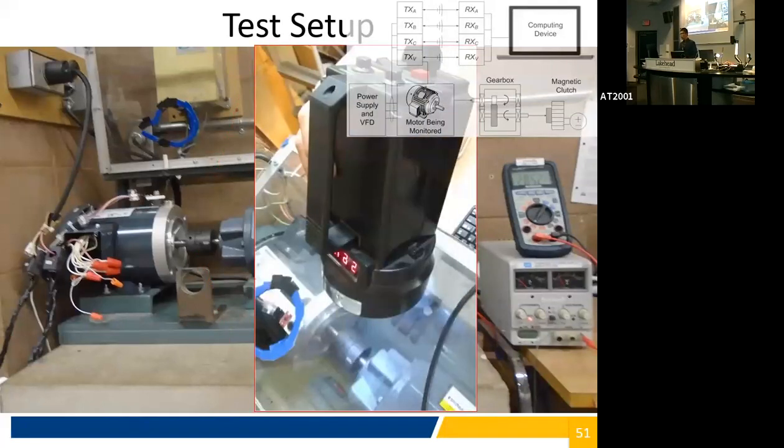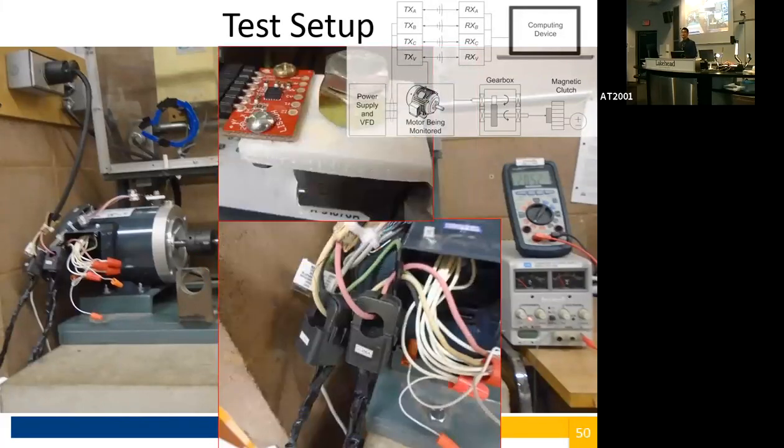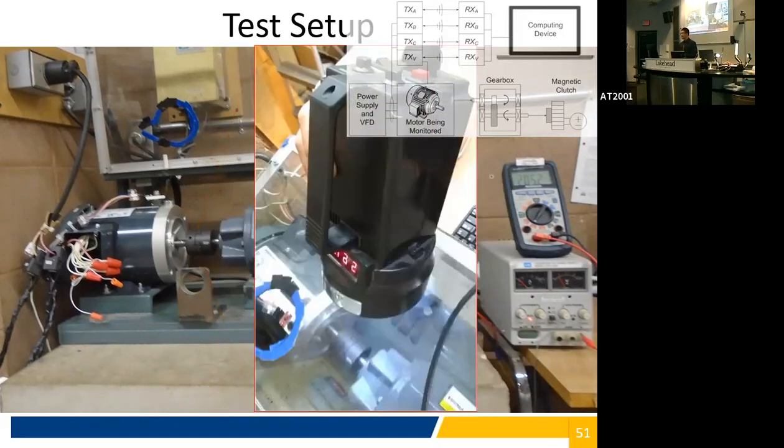And also, since the vibration was used to determine the speed, we did extra steps to confirm the vibration really corresponded to speed with a strobe sensor. So this is not part of the smart sensor system, but it was used as an additional verification where we shine a strobe light of a known frequency, and if a certain sticker attached to the shaft appears to be stationary, then we can verify the speed further with an additional sensor.